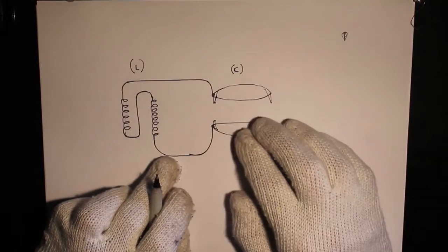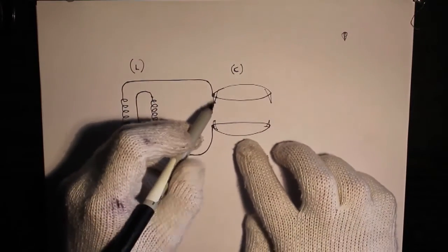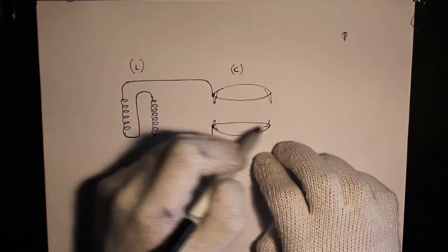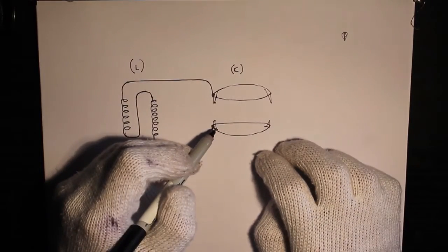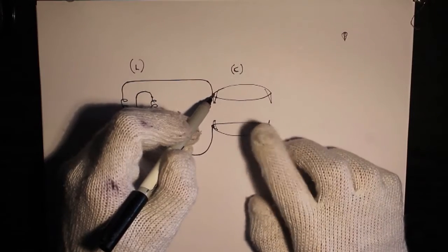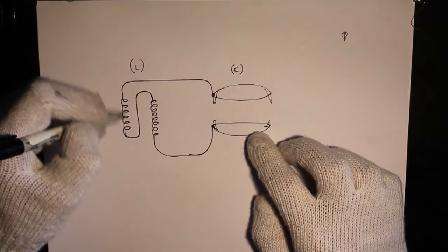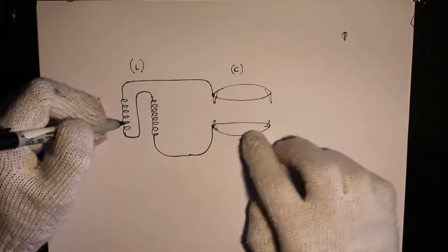It's tuned by the capacitor value set with these rings. You can't really adjust it, because it occupies another function. It's not just a capacitor, we're just using it as one. But what you can do is tune these inductors.